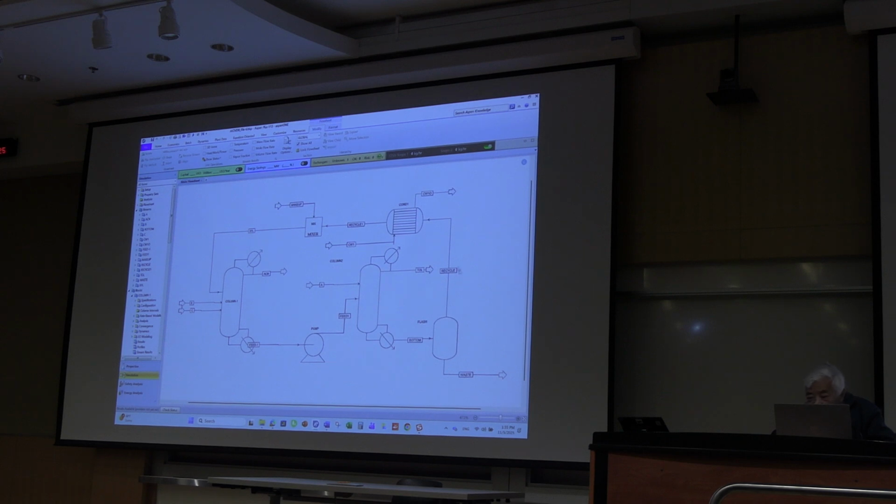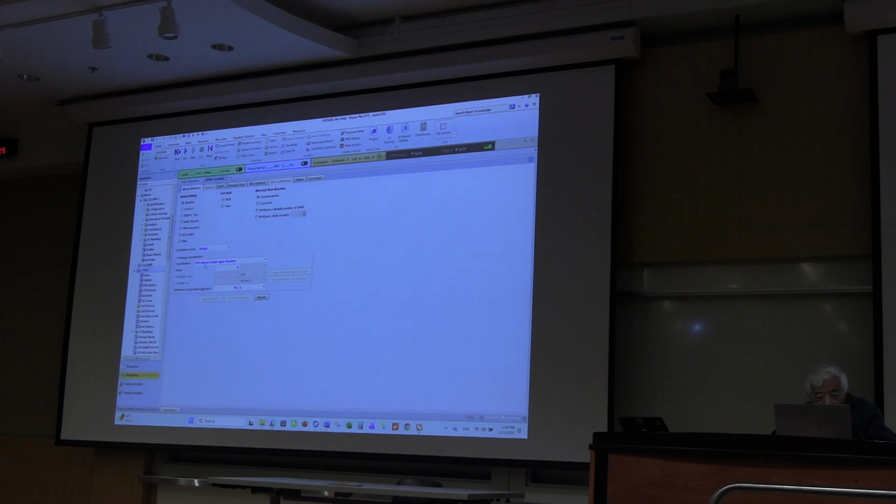The first thing is you add an exchanger using cooling water to condense the vapor to the liquid. Look at this exchanger. Hot stream outlet vapor fraction 0, fully condensed. Your U method for condenser, I give you a heuristic handout, 0.85. For the boiler it is 1.14. Liquid heat transfer 0.28.